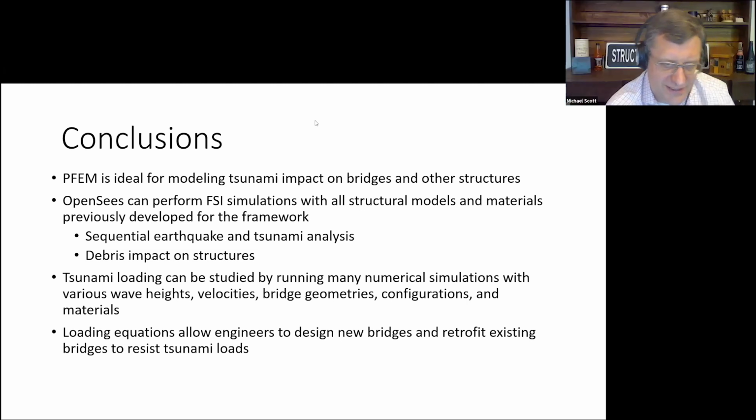Oh, that's a good question. Performance levels. Okay. So I guess we can incorporate it with performance-based methodologies for sure. But then in terms of performance levels, you could think of it as immediate, kind of like the buildings, right? Immediate occupancy, i.e. for bridges, immediate travel over the bridge. At the other extreme for buildings, we had collapse prevention, but for a bridge that would be, don't lose the superstructure to a tsunami, right? Keep that tied down and not in the river. But in between, right?